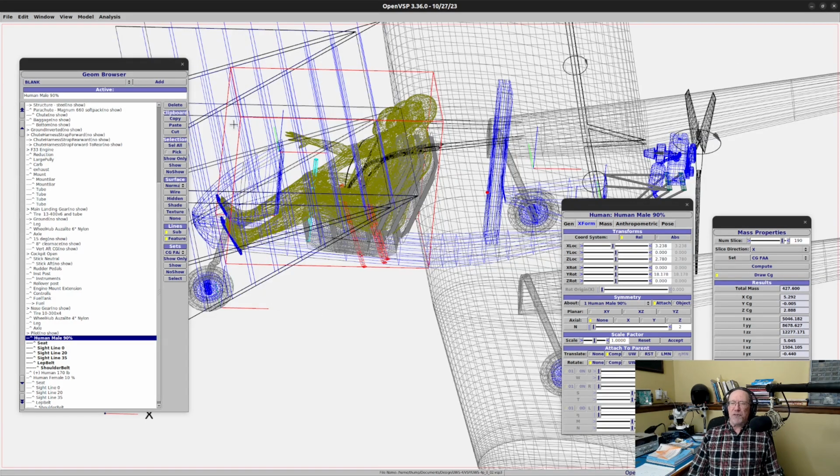So at the end, this front part of the fuselage will end up determining where that CG goes. And I want, at least for the 170-pound pilot, to have that close to 25%. I would prefer to have it close for the other size pilots, but my guess is that for the really light pilot, it's probably going to move aft. For the really heavy pilot, it's probably going to move forward. And that's where my aft and forward CG limits come into play. So I'm going to have to figure that out.